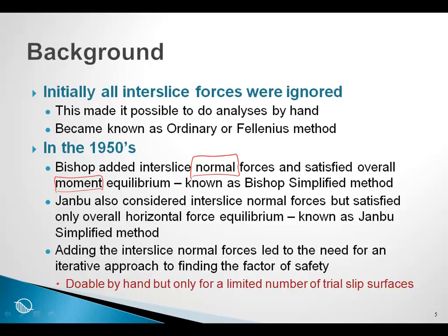Very much at the same time, or close to the same time, Janbu also considered interslice normal forces, but satisfied overall horizontal force equilibrium. This has become known as the Janbu simplified method.